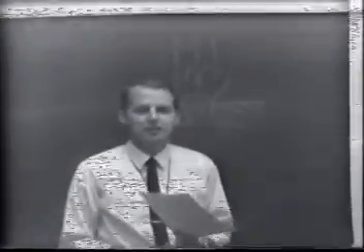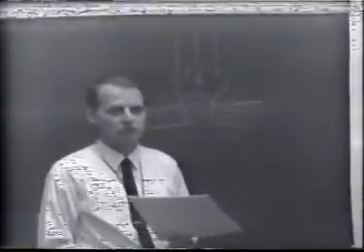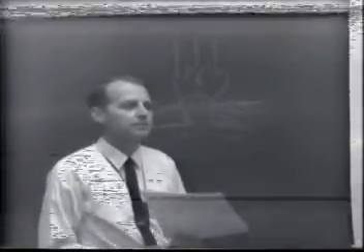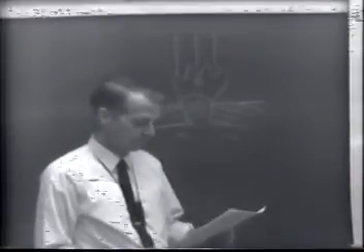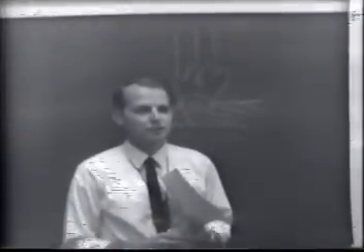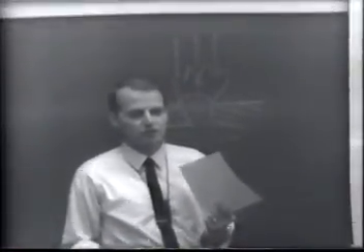In extinguishing an AC current arc, of course, we have one distinct advantage, in that the current in a 60-cycle system goes through zero twice every cycle. So at this point, the arc actually goes out, and then when it starts the opposite polarity, it starts up again. It has to be reignited. So as you can see, our objective here, during the period when it goes through the current zero, is to try to increase the arc length and increase the dielectric strength in these periods of current zeros, so that at the next current zero, there isn't enough voltage across the two contacts to reestablish the arc, and then the arc would go out.